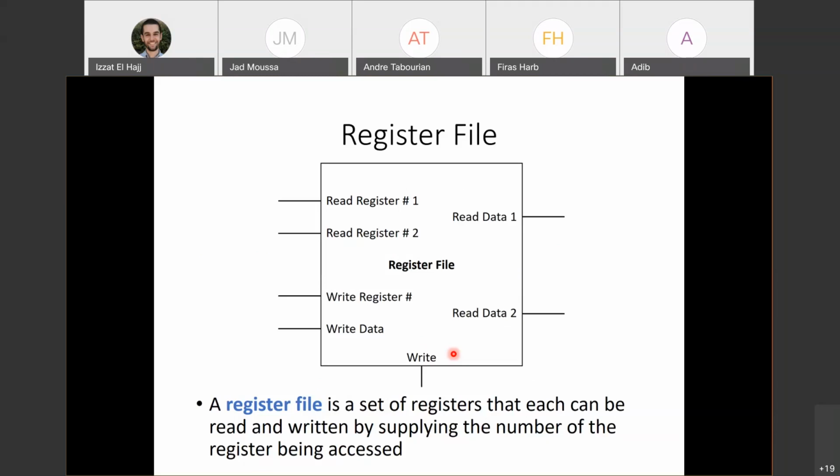If I want to keep the value for multiple clock cycles, what I can simply do is have kind of the clock, and we saw this later on in last lecture, where we guard the clock with another AND gate that has another signal. When we set that signal to 0, it prevents the clock from reaching the register. And in that case, that value will stay there for multiple clock cycles.